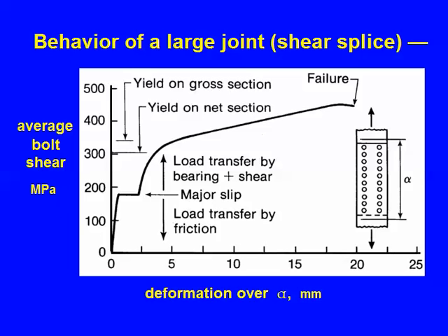And in the initial region, from 0 to, I don't know, 180, it's fairly linear. Depends. A lot of these things depend on the proportions of, in this case, your plates. But at a certain level, the slip resistance will be overcome, and it moves suddenly. It can move in a series of small slips, or it can move in one big slip or maybe two smaller slips. It doesn't matter. As far as you're concerned, you get to the same point. In this case, this would be a deformation of, let's say, 3 millimeters. Okay? So there we are. It's slipped.